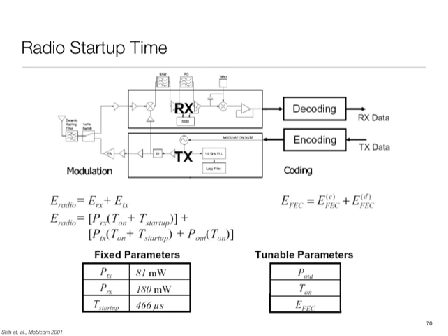The closing point I made last time was that just like in CPUs, we face this issue that depending upon the parameters, you may be in a regime where you should just operate at the right speed. That's the optimum strategy. Or you may be in the regime where you should operate as fast as possible, finish, shut the thing down. And just like in CPU, in radios, you have the same possibility. I can run the radio at a very fast speed by changing the modulation and coding scheme so that at a higher rate you are stacking more bits into each symbol that goes over there, but that comes at a cost. And so in many cases, you may be better off going as fast as possible and shutting it down.